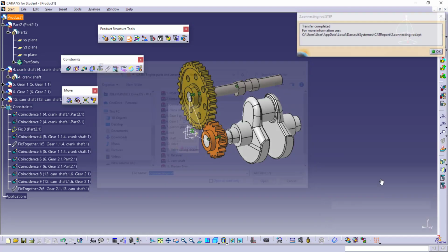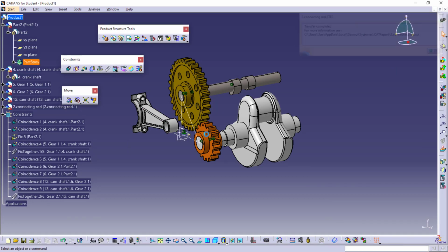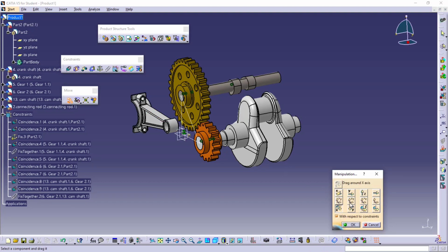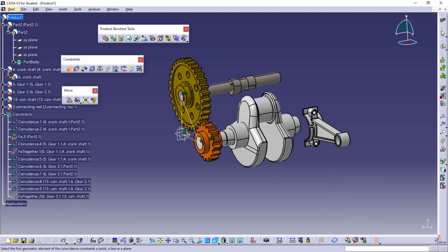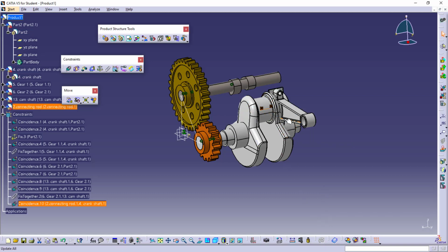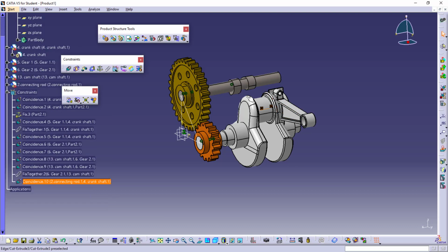Yeah, connecting rod, I'll add it here. To mate them, so first thing is I'll use the move tool and orient it properly. Okay, and now I can use the coincident mate again. So hover on the model to get the axis here as well. So update this. Now I need to place it exactly at the center of this one, right?